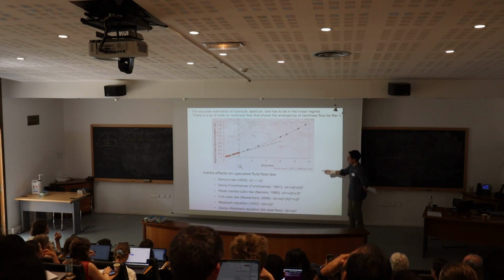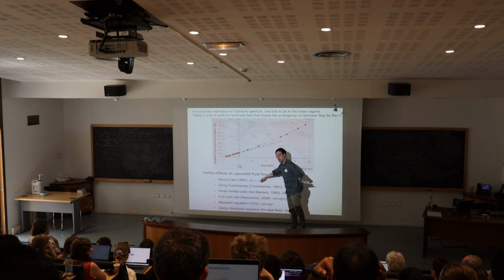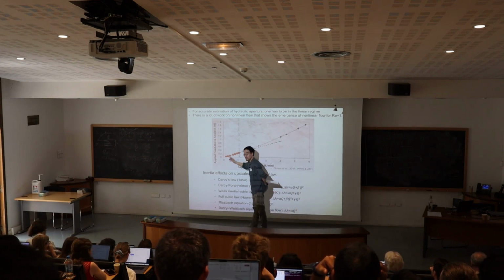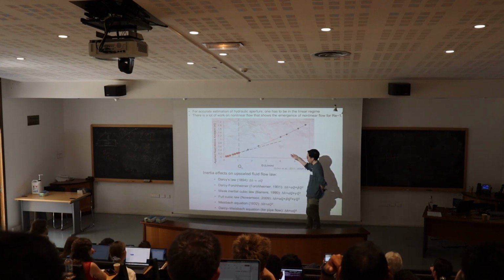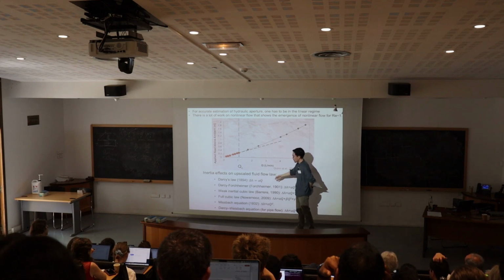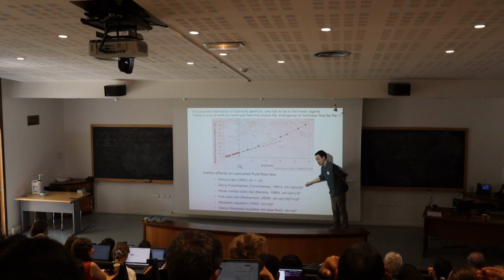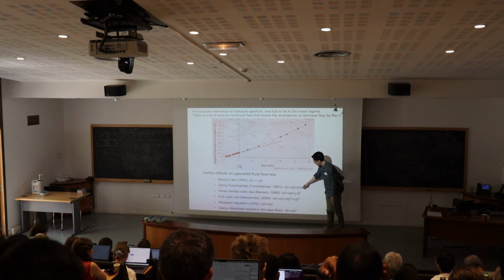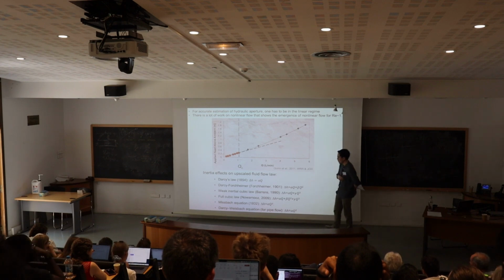Okay. So Darcy's law or cubic law that we derived is simply saying volumetric flow rate is proportional to the head gradient, right? And that's this linear flow regime. The most famous or widely used formula for inertia regime in fracture is the Darcy-Forchheimer equation, which was proposed in 1901. And it's basically just adding the second order term. And this was empirically discovered. And it works quite well, so that's why people use it a lot. And this is just considering the inertia head loss by adding the second order term.